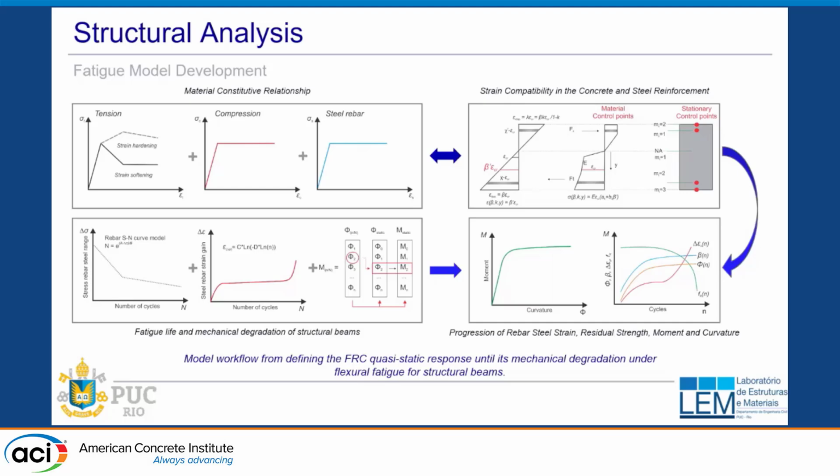And the best way of doing it, for this type of model, is probably to obtain an SN curve for the steel rebar. And from that, you can add it to this restraint curve that we have.